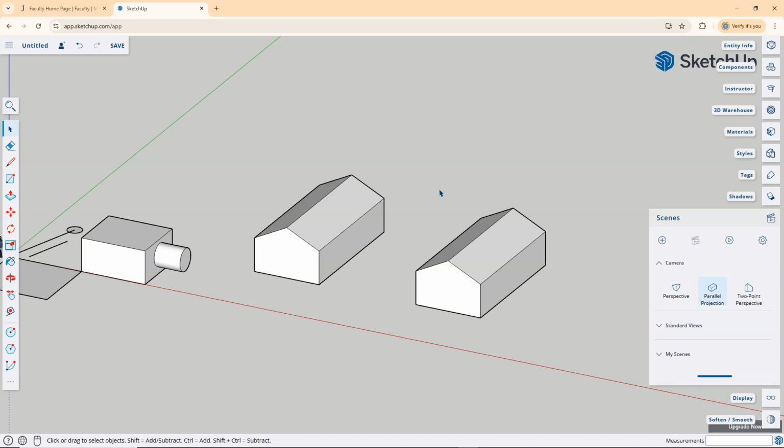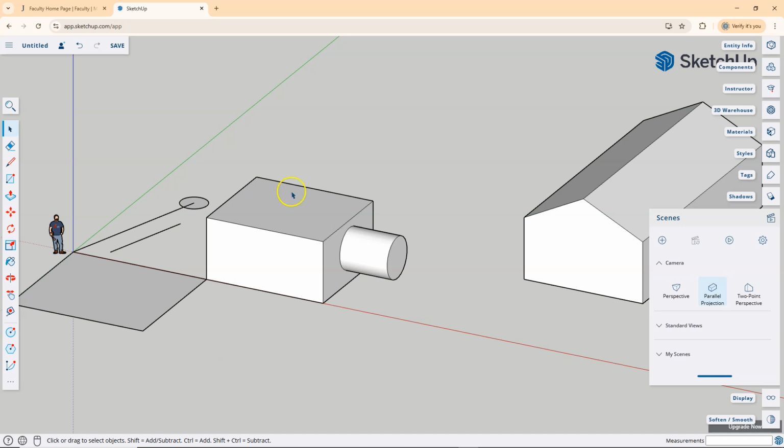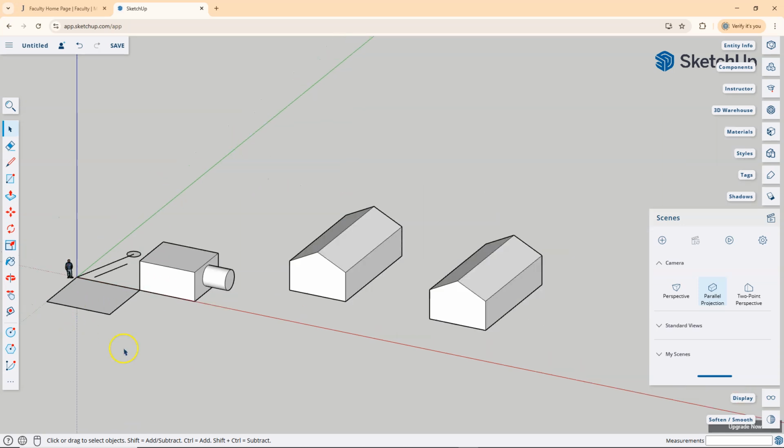And that's a key element of working in SketchUp, because it is individual objects, and any new object we create attaches to that. Sometimes we don't want that behavior. Sometimes we want the three-dimensional objects we create to remain independent of the things that are touching them. And SketchUp does fuse to anything that's touching it. So any SketchUp object is going to fuse to another SketchUp object if they're touching. And we saw that demonstrated over here when we created that second rectangle.